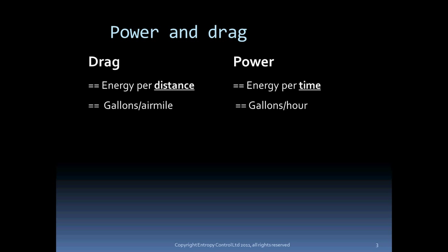On the power side, you'll know, for instance, that a 180 horsepower engine operating at 75% power, that is, delivering 135 horsepower, will consume a little over 10 gallons per hour. That is true for pretty well any 180 horsepower aircraft at any speed and altitude.